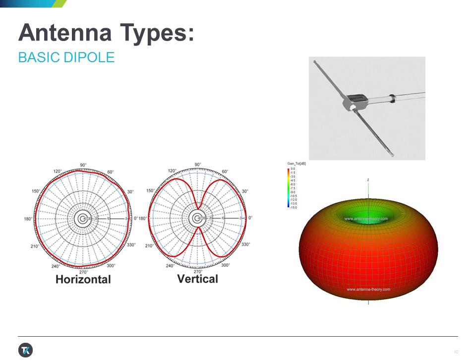In this slide here, we're looking at the coverage pattern of a basic dipole antenna. Essentially, this shows us what the transmit and receive pattern for this type of antenna would be. In this example, we can see that it's not directional, but rather omnidirectional. So there is no directivity when we're using a dipole antenna. This type of antenna is, however, very useful as we get closer and closer to the source of interference. While it may not be directive, it has a good all-round antenna pattern.